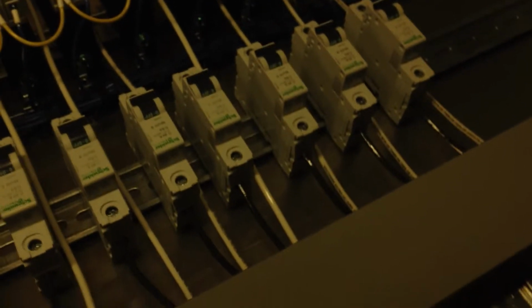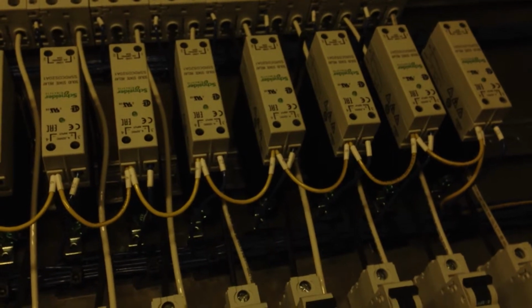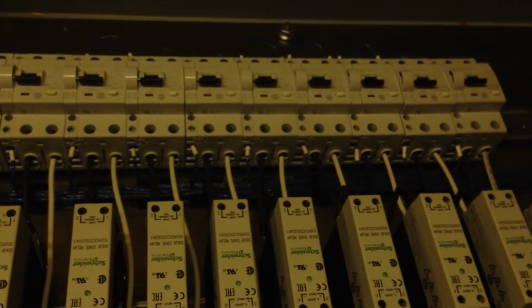Control transformer, I'll put fuses in it in just a second before we ship it out of here. There's your PLC. Your RTDs hook up along the left-hand side. You bring your wire on and hook up your RTDs there. Each circuit has a circuit breaker, which will be labeled and tagged. And it also has a solid-state relay. And even down below it has a GFI terminal block. I'm upside down here, so it may look a little odd, but anyway, thought this might help.